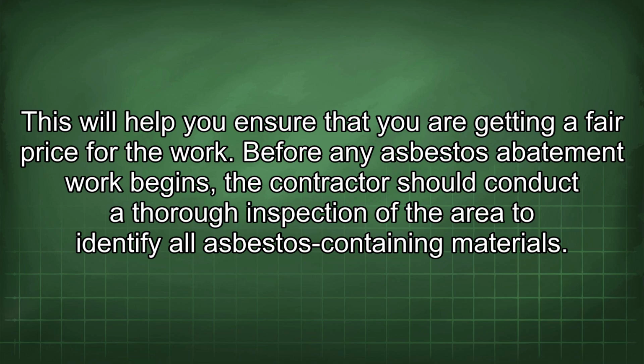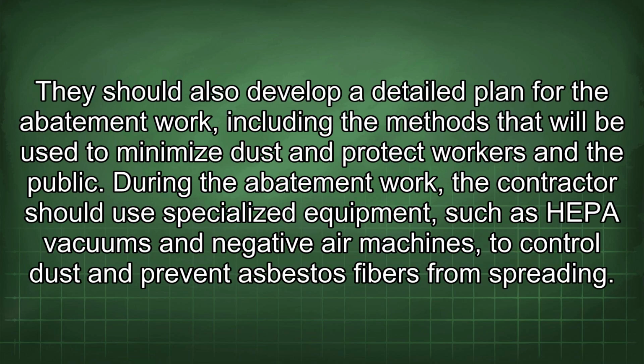Before any asbestos abatement work begins, the contractor should conduct a thorough inspection of the area to identify all asbestos-containing materials. They should also develop a detailed plan for the abatement work, including the methods that will be used to minimize dust and protect workers and the public.